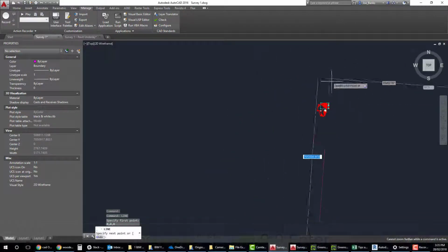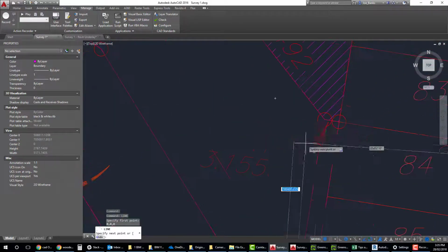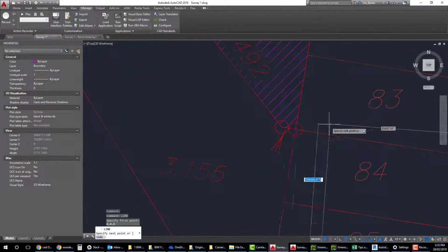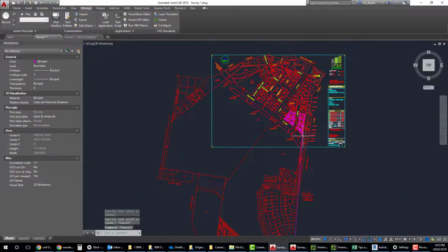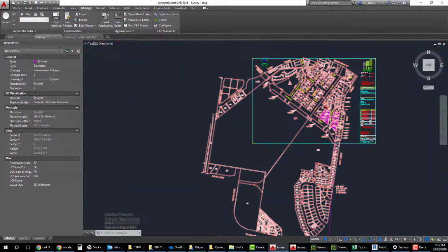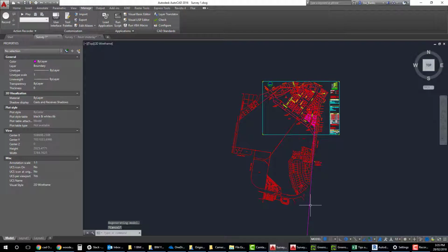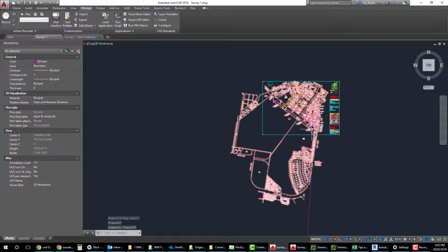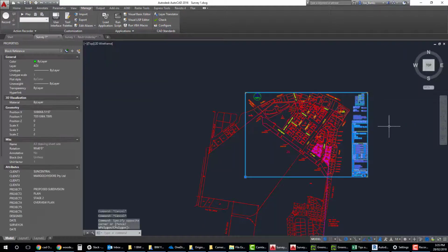You've now got a line going from the 0, 0, 0 point, and we will connect that to, I'm going to just pick a point over here and say that is my local datum. So we can see that's where the CAD origin is, and this is where our geometry is. Now for Revit, this is too far away from the origin point. We need to get all this geometry down to that other origin point at the bottom. So we can delete all of this stuff.